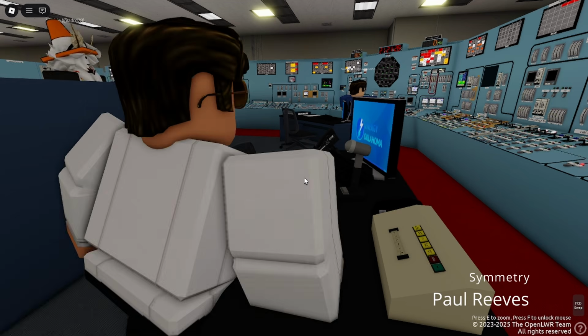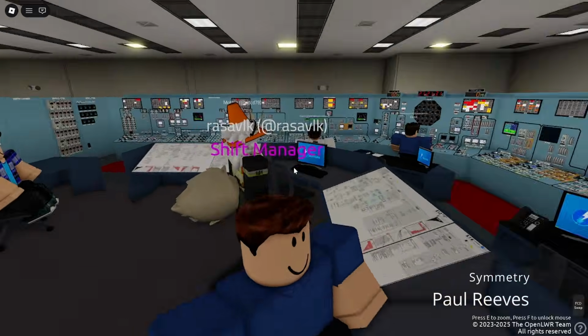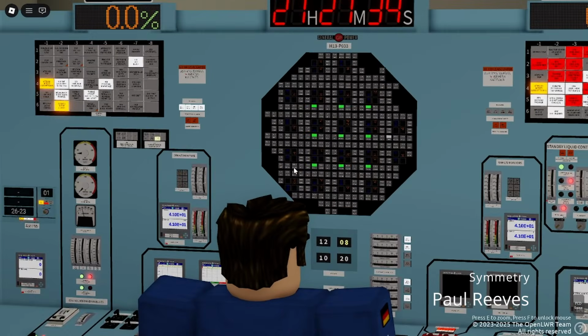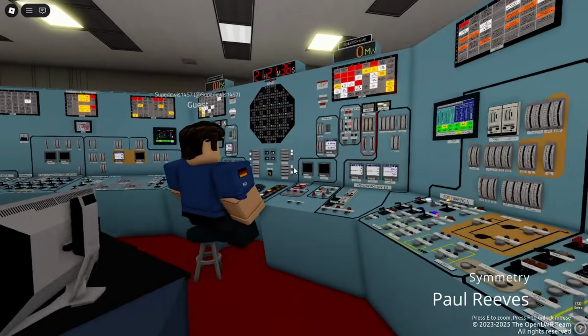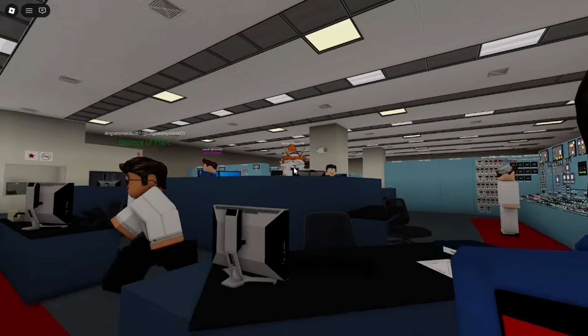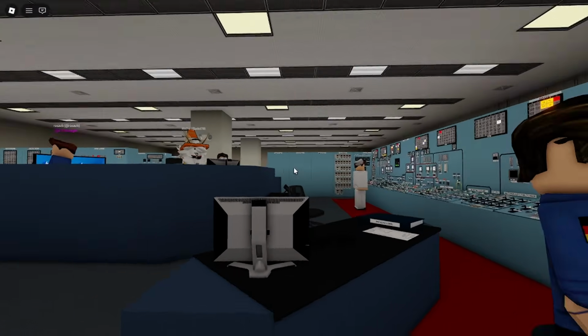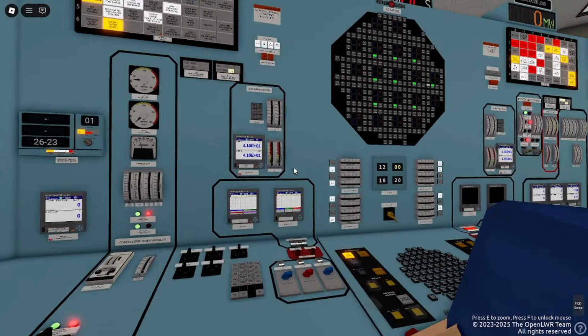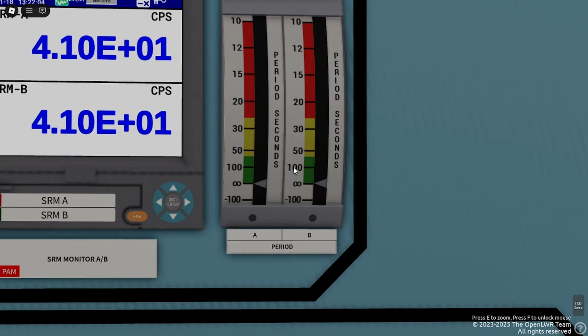The reactor protection system, also called RPS, consists of mechanical relays that trip in an unsafe condition. You can hear these throughout the video. And hydroaccumulators, which are filled with pressurized nitrogen. During a scram, the nitrogen pushes a piston which pushes water into scram lines. The water moves control rods within a few seconds into the active zone. Yes. When fully inserted, SRMs indicate less than 100 counts. Understand, fully inserted SRMs indicate less than 100 counts. That is correct.